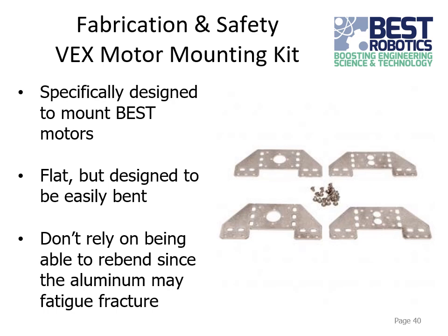Outward, if you have the room for it on your robot, is usually easier, because that means you can get to the screws and screw those screws on the mount without having to take the motor on or off. Because if they're inward, then they're kind of hidden underneath the motor, so you'd have to take the motor off first. But if you bend it one way and you decide you want the other way, then it's too late. You can't really rebend it. You're kind of stuck with what you got at that point.